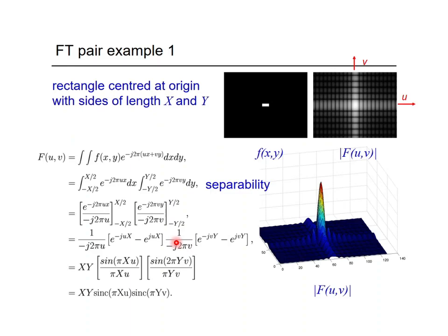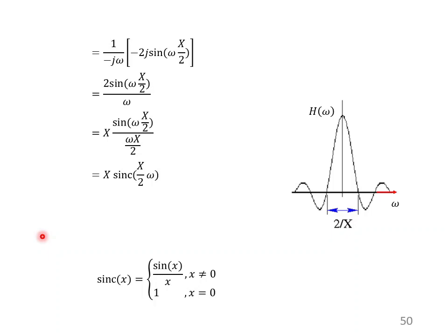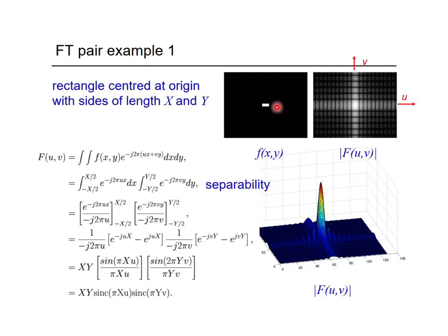Now some important Fourier transform pairs. You have seen the univariate box function, right? Let's take a look back. This is the one-dimensional box function, and its result is a sinc function. Now let's go back to the 2D data. For the vertical axis or horizontal axis, either is a box function, and its result is a sinc function, but for two dimensions.